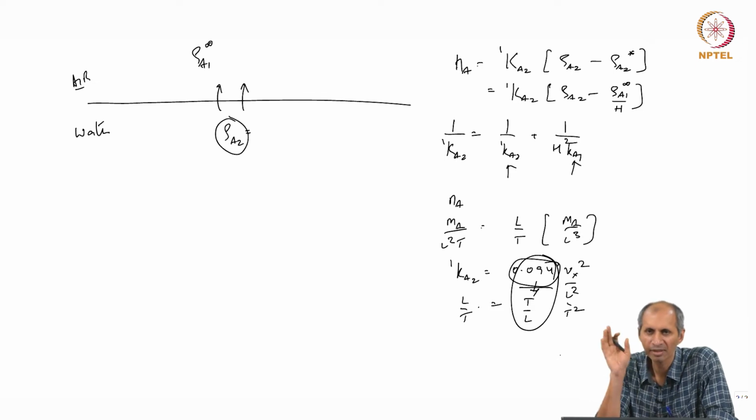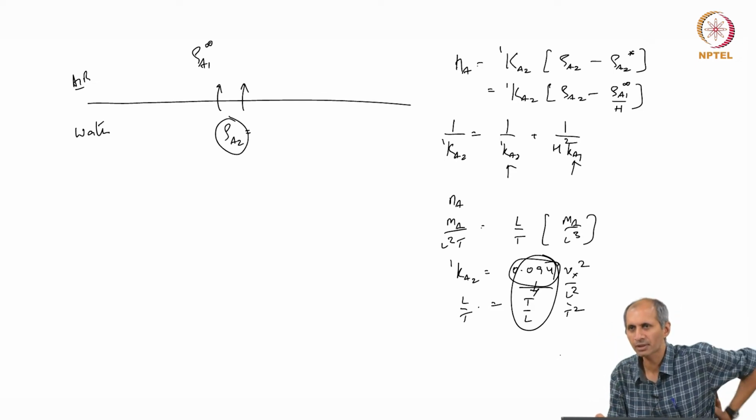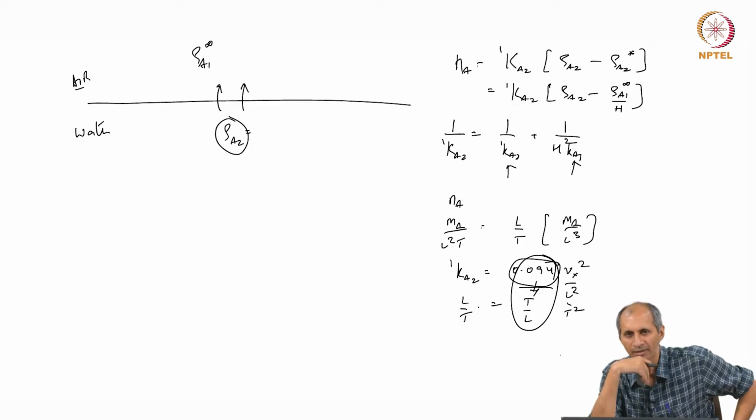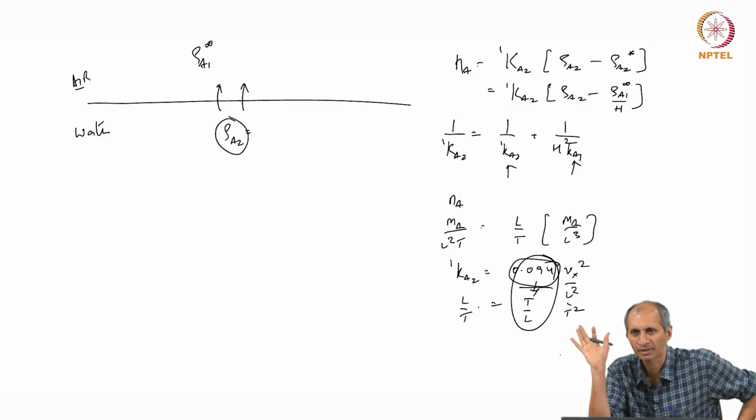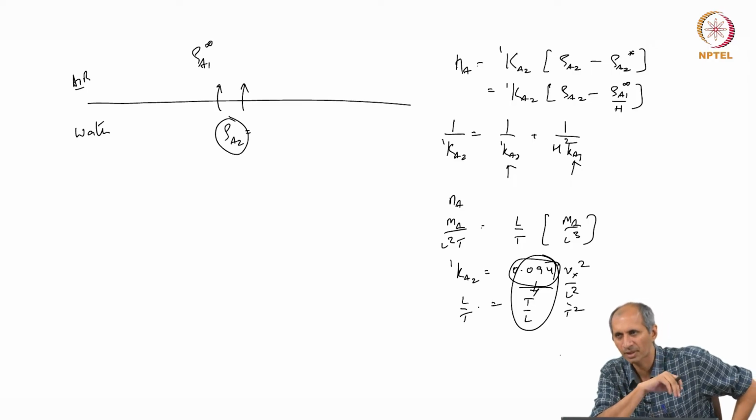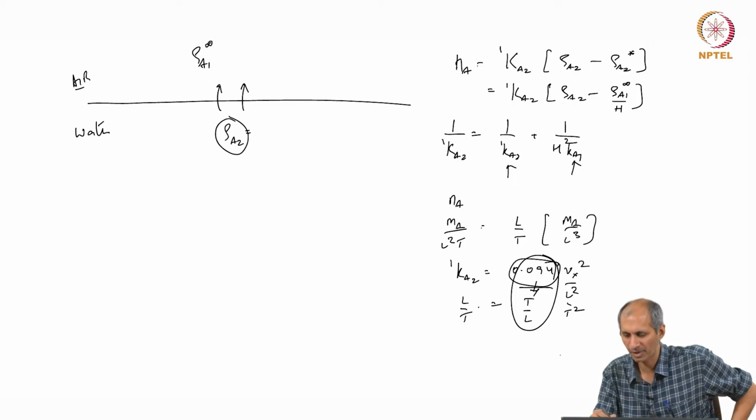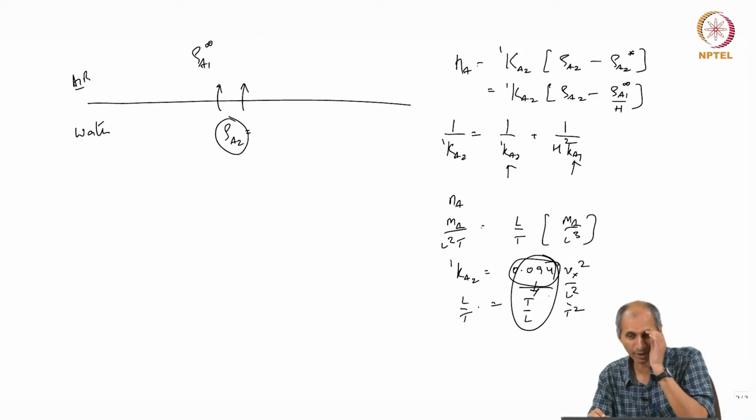What they are essentially doing is they have measured the mass transfer coefficient and plotted it against the velocity of air, and this is the correlation they are getting, and that is it. It is an empirical correlation, and you have to follow whatever they are saying very strictly. You can't make your own assumptions and all that. This is what they have given.